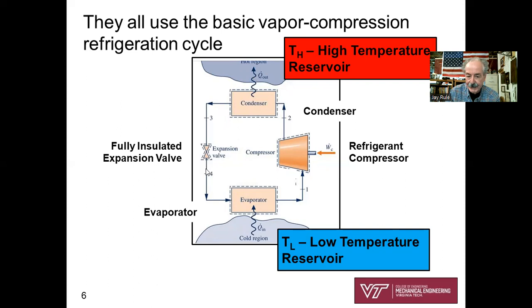And it turns out that refrigerant gets very cold when it goes through this pressure valve, expansion valve. Pressure drops dramatically. Then we go into the evaporator, and that's where the action is for an air conditioner or refrigerator, where we absorb heat from the cold space. So 4 basic components of the vapor compression refrigeration cycle that you should have in your head: a compressor, a condenser, an expansion valve, and an evaporator. You need to commit that to your memory.